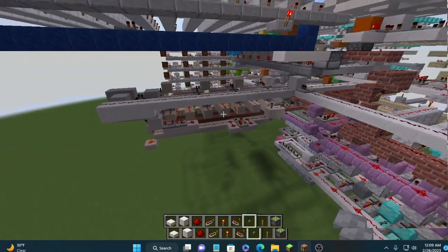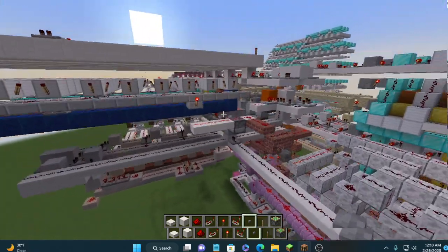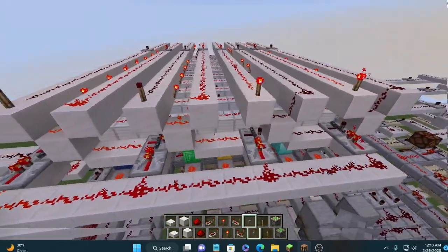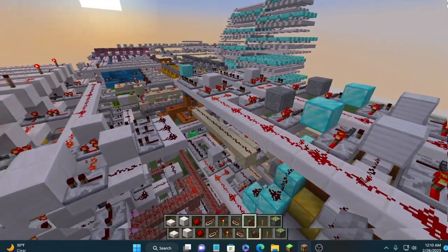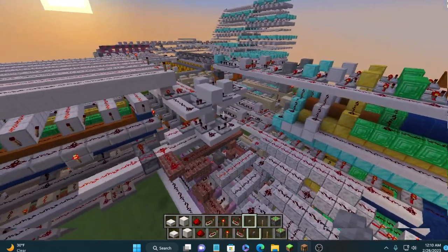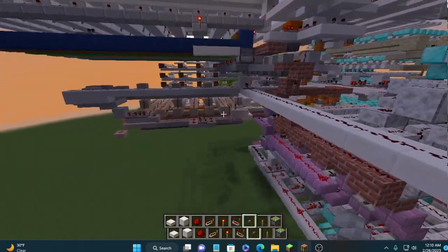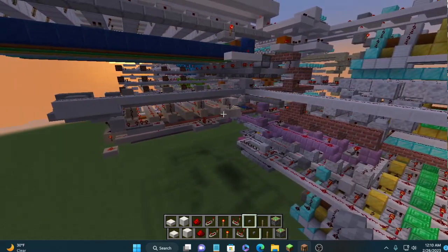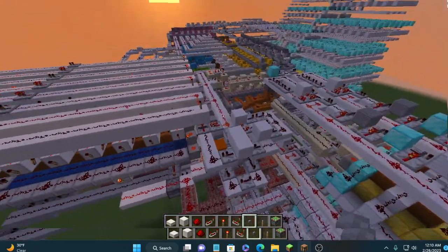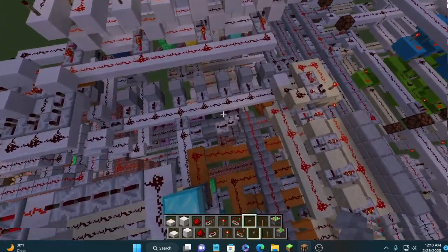One's down here on a lower decoder that handles all the functions. The other one's up top on this bigger decoder that writes all the digits and the little C to the displays up here. And when we write them, this guy only cares about numbers, and this guy only cares about functions. He only sends out pulses on different lines to tell different shift registers to move or whatnot, and he just converts 4-bit digits into 7-bit serial data.